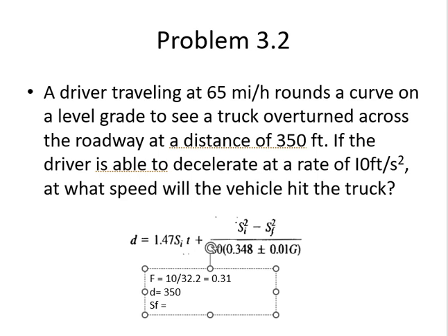Perception reaction time, the normal value is taken as 2.5. But there is an entire table. If you go to the previous slides, you will see an entire table where perception reaction time is given according to different situations. For the time being, just take it as 2.5 seconds. I'll show you another table for perception reaction time as well, but for the time being, 2.5 seconds.